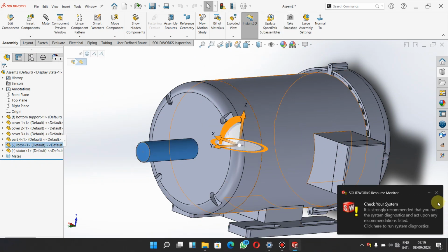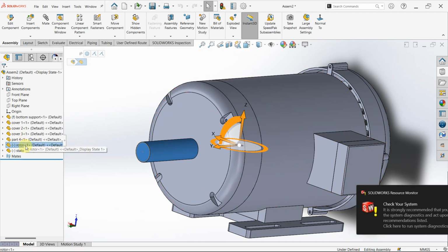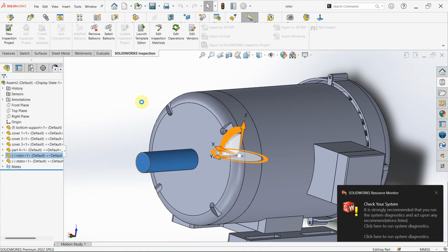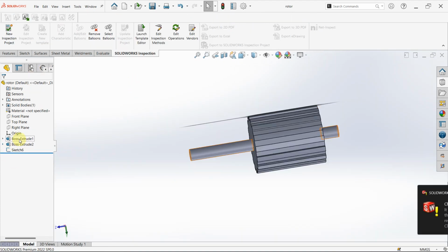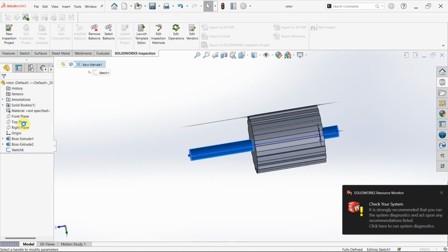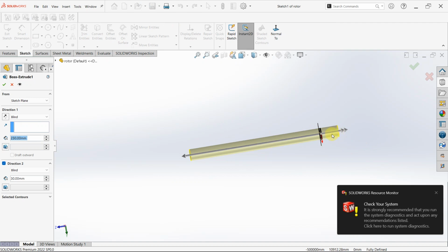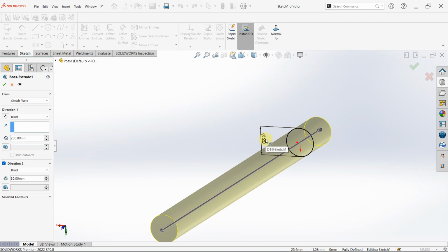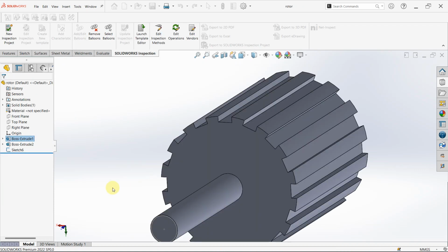Root tail. So this is going to be opened, and this sketch was created using a plane of 20 mm, then extruded using two directions. The first direction was 20 mm, the second direction was 30 mm. You can just use 260 mm in one direction. Probably it was shortened before and I wanted to extend it while modeling.